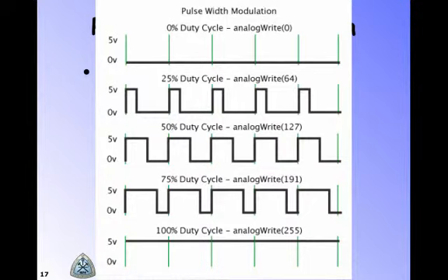So PWM, or pulse width modulation, has really come on as the preferred way to drive smaller DC motors and servos. There are other ways. In the old days it was done with linear circuits, and if we were using other kinds of motors, we could be using what is called variable speed drive.